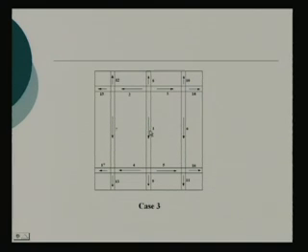Then it depends on slowly motivating them to work accordingly, though it makes things a little difficult. The procedure followed is that the sequence is given in the drawing sheet. The sequence is drawn on the plate, just marked 1, 2, 3, 4, 5. So he knows from where he should jump to which place and do the welding like that.